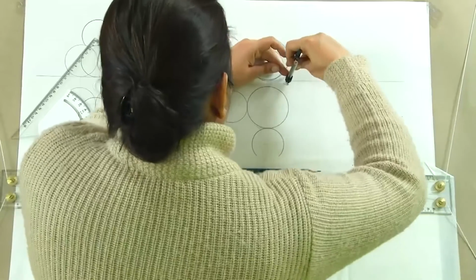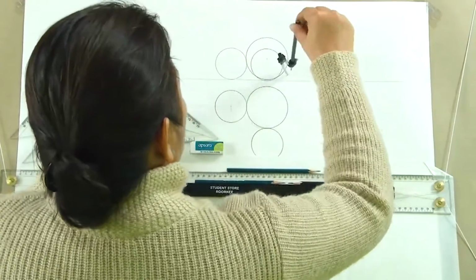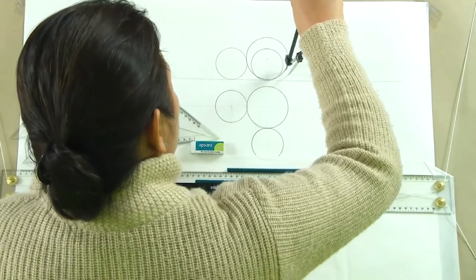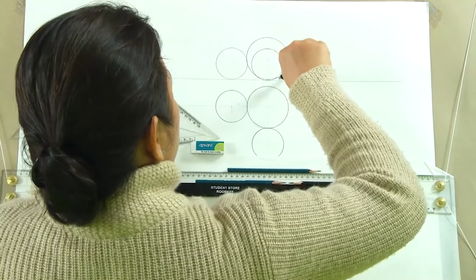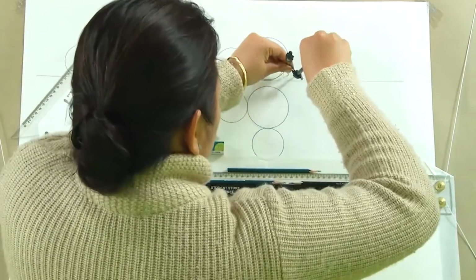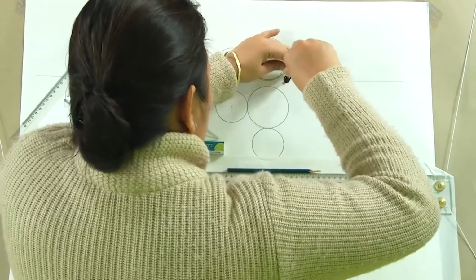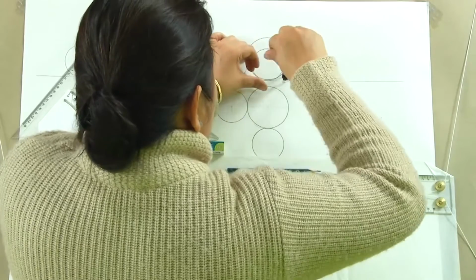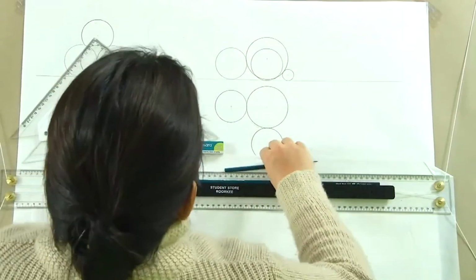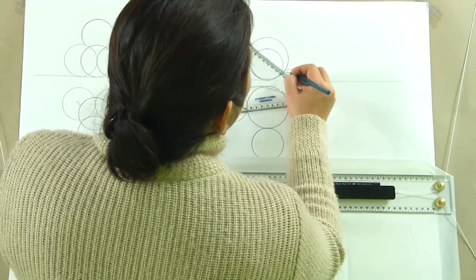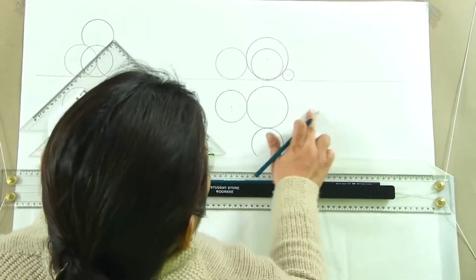And taking a radius of 1 centimeter and this as the center, we will now draw the smaller sphere. So, this is the smaller sphere, a very small sphere which we will be seeing in the elevation as this. What we actually have are these straight lines which are joining the centers. Now, this line again is parallel to VP.